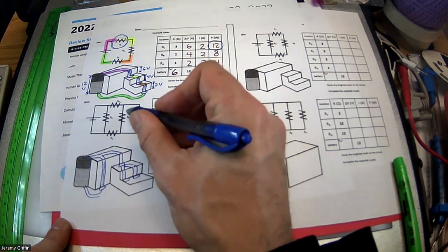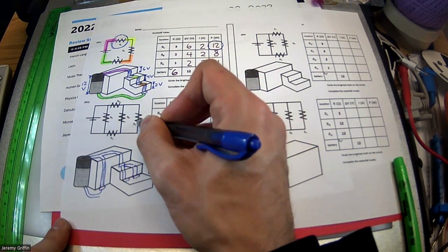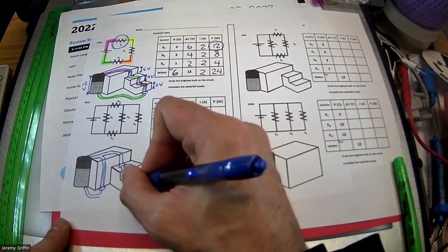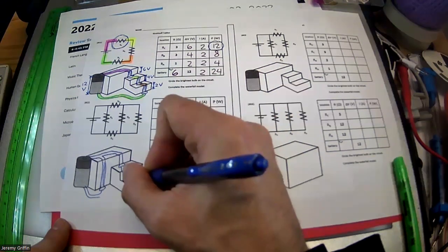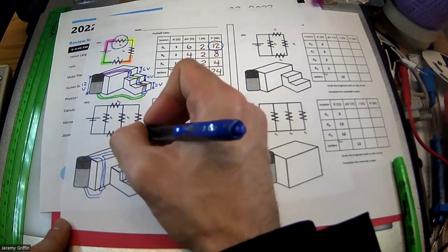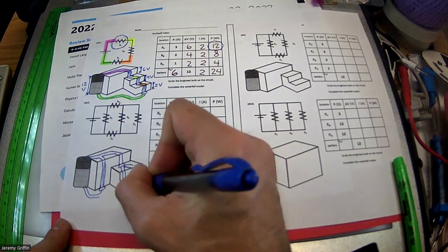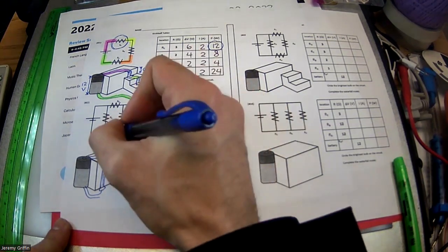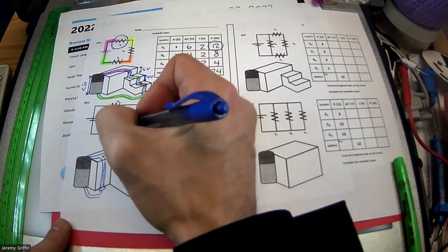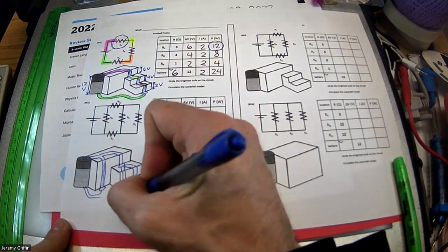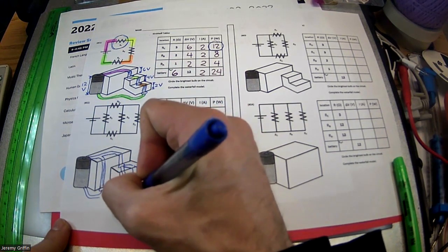Then the current that goes through resistor B and resistor A immediately joins back together at this junction, so I'm going to draw these streams coming back together. And one more voltage drop across resistor C, a splash. Any current that goes through resistor C, now the voltage has dropped to 0 and it goes back to the battery, let's say back to this pump.